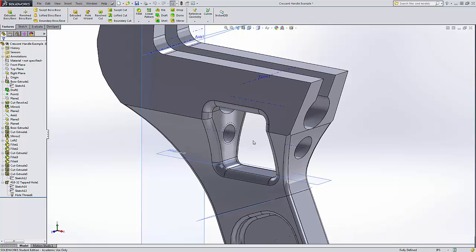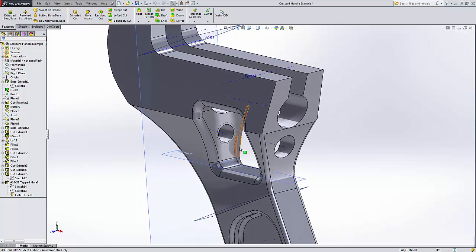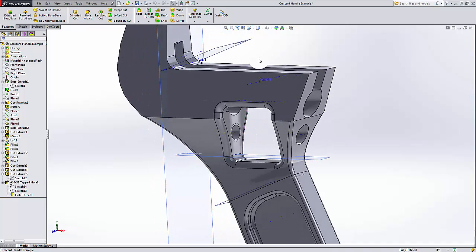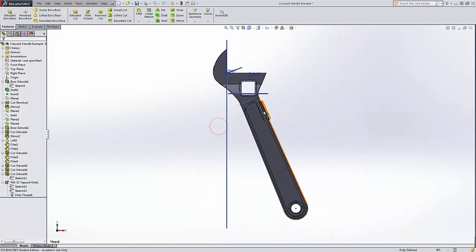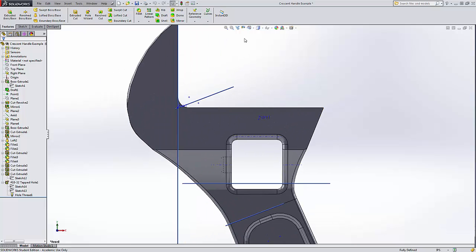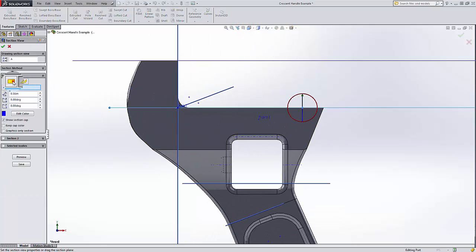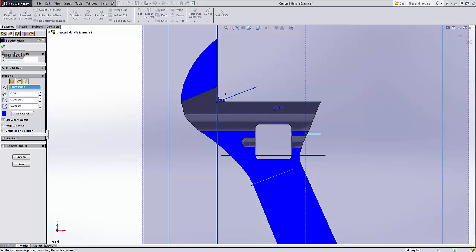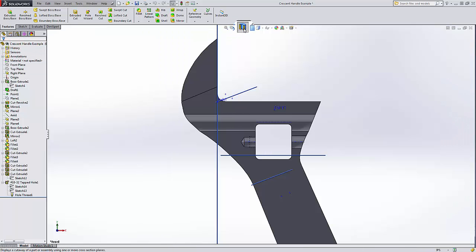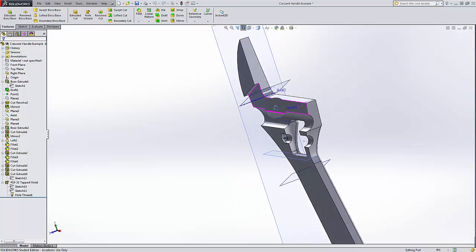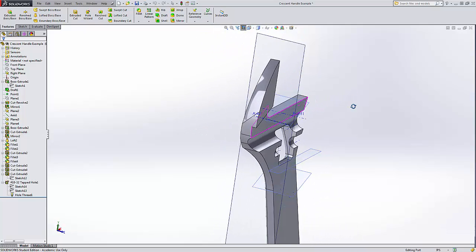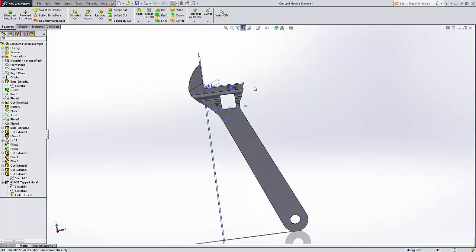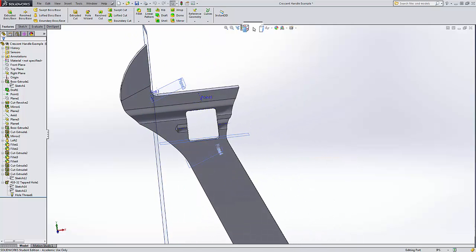that's cut. I will show you how to make some helical cuts, which are some threads, but this should be good enough. Let's look at it from this perspective and zoom in with our front plane, and you can see right in here that the threads go this deep, but it's just cosmetic. Again, you don't actually see the thread cuts. I really like using these section views. It can help you get a great idea of if you're actually making what you want to make.